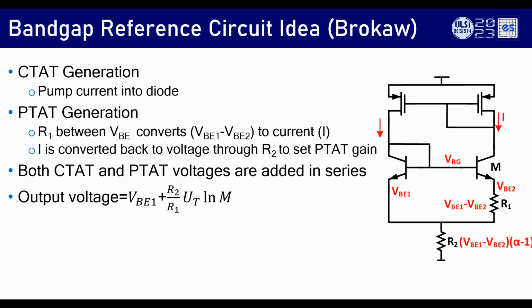For that, initially the first bandgap circuit people developed is the Brokaw. The core is very similar to what we have. You have an NPN. Let's say that in a technology you get NPN diodes. During that era it was all a BJT process. We had NPN transistors. So the idea is, look, I put a lower current density in one branch, VB1, which is higher. Inside VB1, I put a resistor and VB2, and I size the BJT m times.